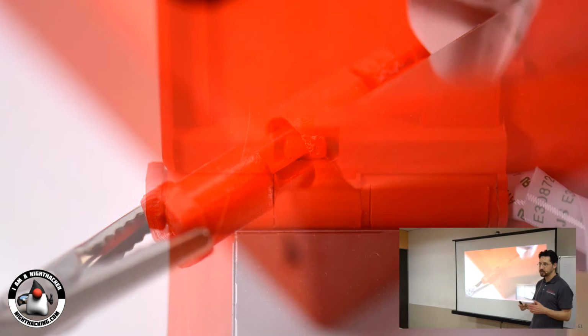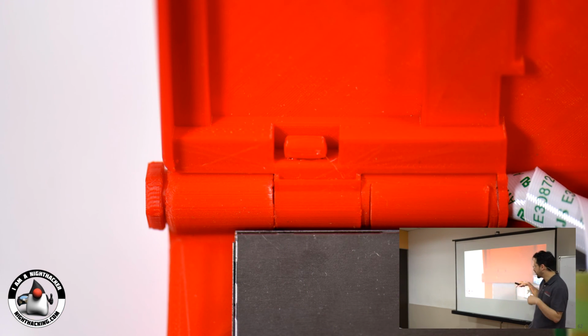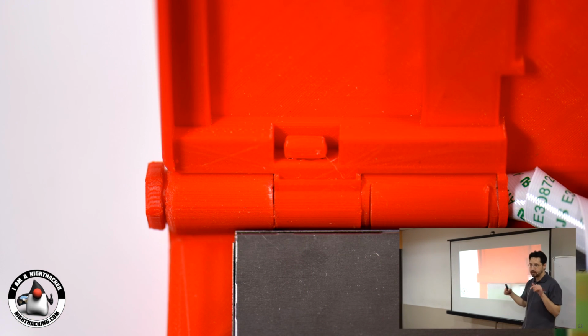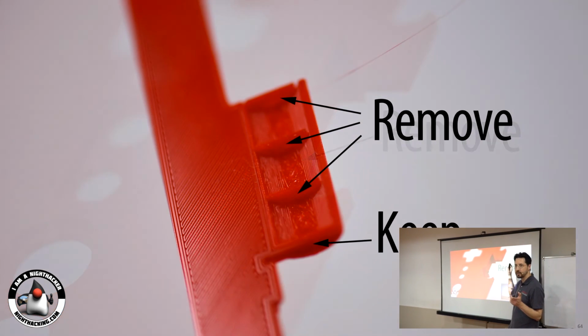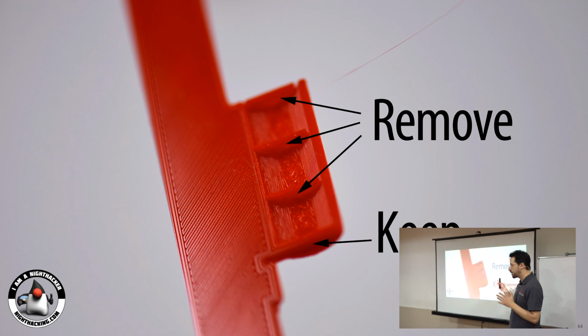And that hole has a slot in it, so from the top you can put down these little locking pins on either side, and then the screen goes on top of this and actually locks it in place. And the same thing for the screen, there's two areas you need support material, here and here. It prints without this, but I found it prints more reliably with a little bit of support material. So I built it into the model with the support material, and you just break it off with your fingers or pliers when you're done printing.